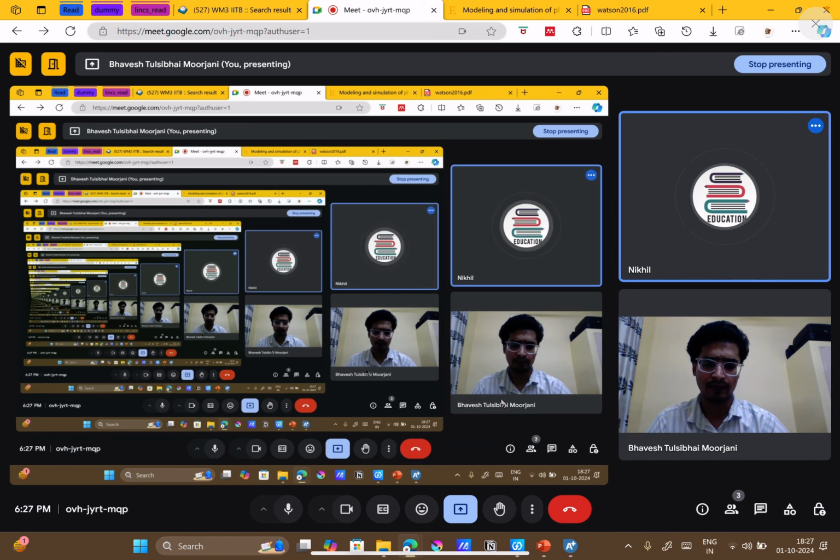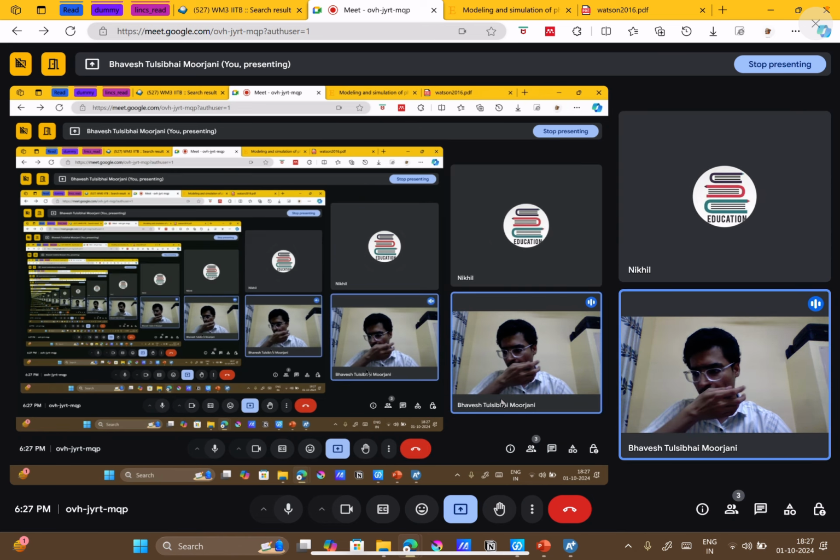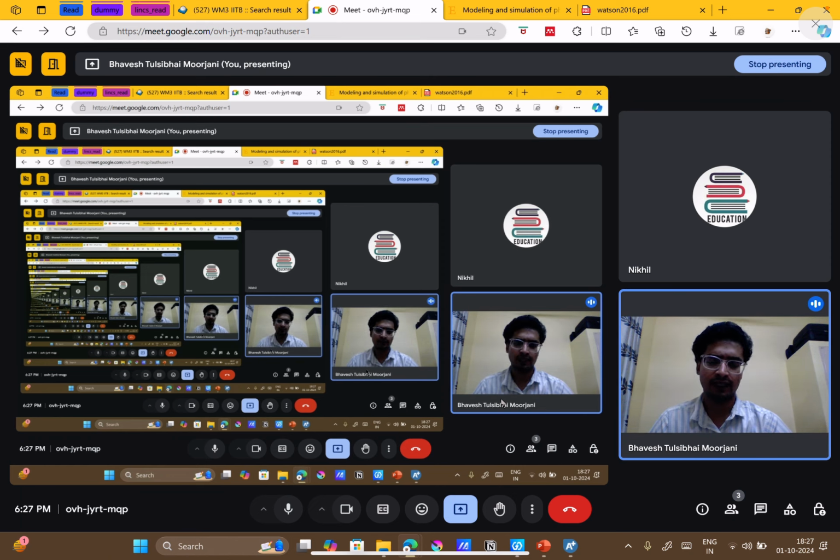Property estimation method. Yes. Okay. So if nothing is given, you can try out this NRTL or unified method. It's an ethanol and water mixture, right? So that should work, and it's a heat exchanger example, right? So it should not make much difference. Property method.